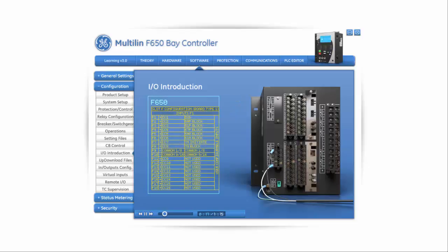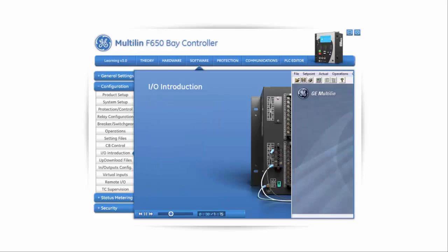Contact inputs. The default configuration of the 650 uses the first logic input, CC1, to detect the breaker position by connecting the 52B auxiliary contact of the circuit breaker. The following 5 inputs block various protection functions when asserted, while the 7th and 8th inputs are respectively used to initiate the auto-recloser from an external source such as another protection relay, and to block the auto-recloser, for instance, when performing circuit breaker maintenance. Other functions can be assigned to the logic inputs using the logic editor.